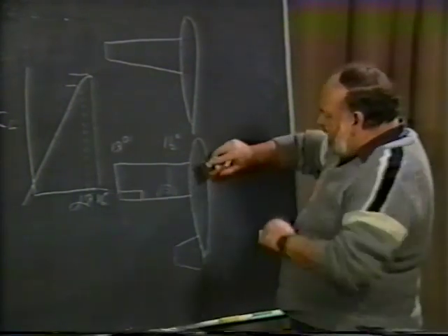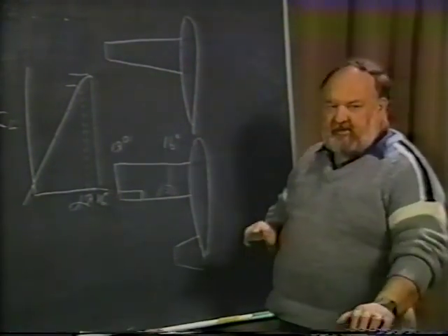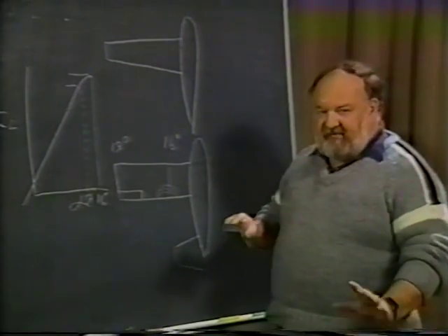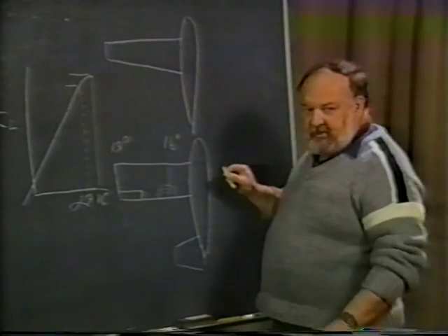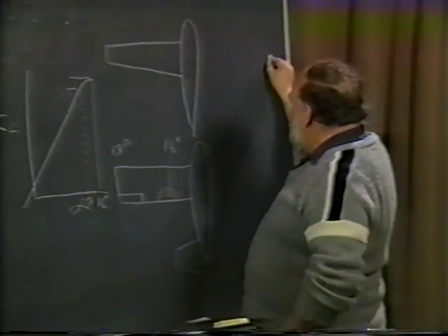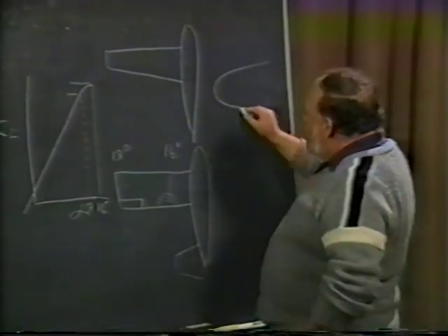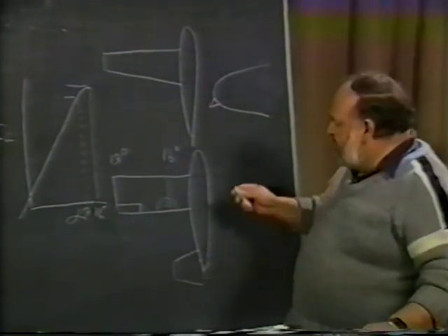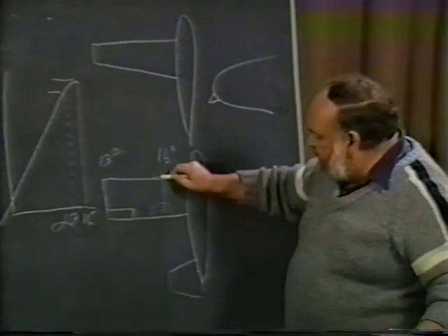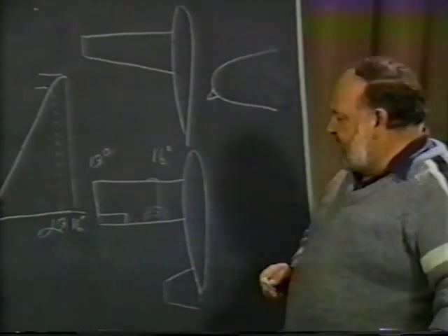For example, if you do something to the leading edge in here, you can immediately affect the stall. A simple way is to put a little stall strip, and I'll show you what that sort of means. I'm sure all of you have seen it, but let's take the leading edge of an airfoil over here. You can actually install a wedge-shaped device that might run 12 inches or 8 inches along the leading edge of the wing.